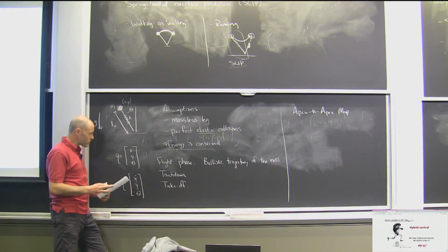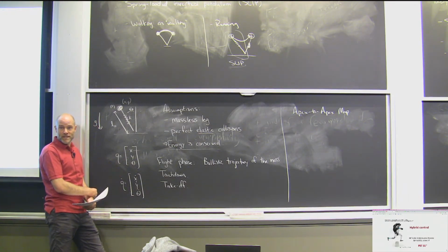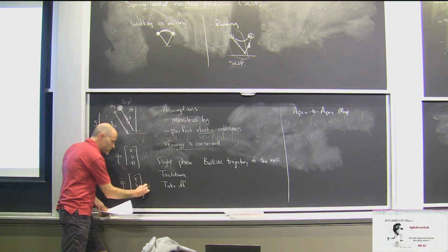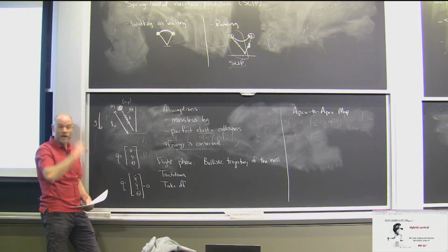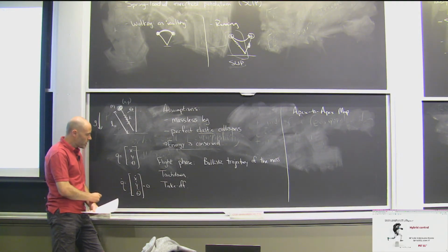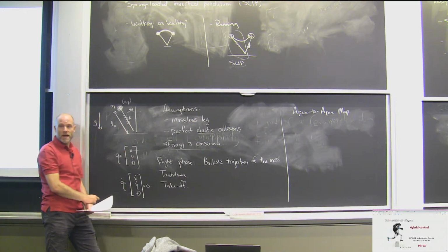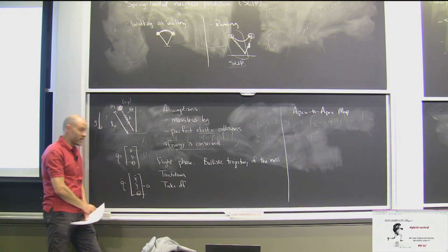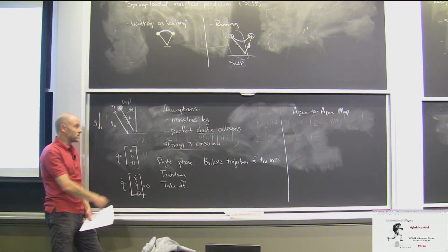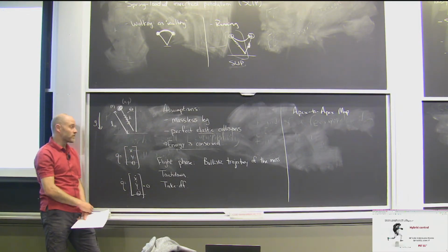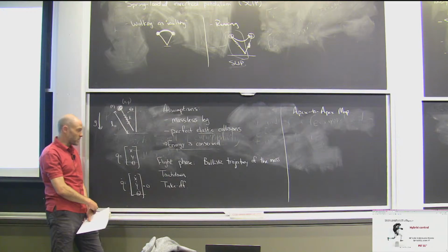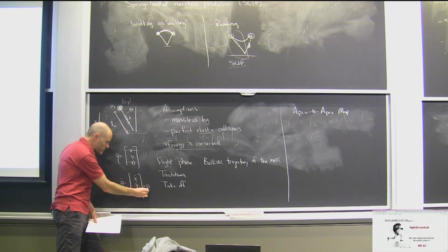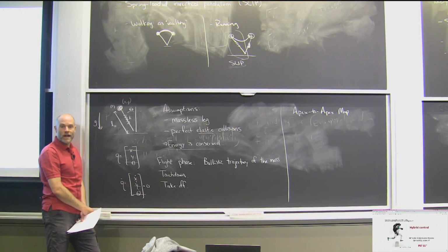Okay. y matters very much. That defines my apex. The apex is defined by y dot equals 0. Right, that's what defines my map. Theta and theta dot, by virtue of having a massless leg that we can set to be arbitrary, we're going to effectively rule these out. Because by this massless leg assumption, we're going to be able to place that wherever we want, so those dynamics are not essential to my Poincare map. Getting close, okay. This one's 0. So now I still have y and x dot.